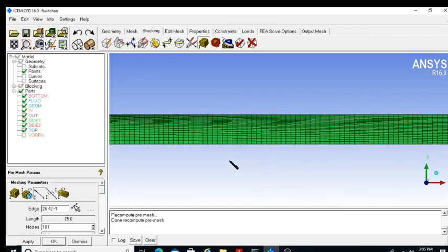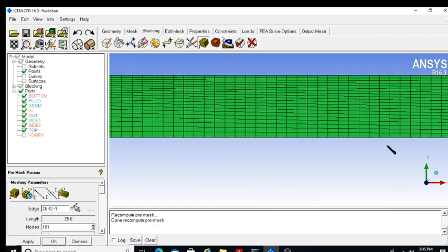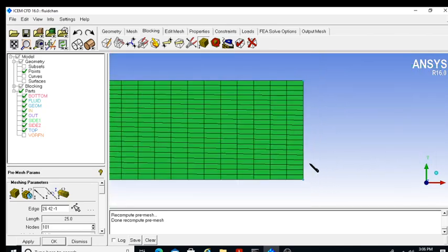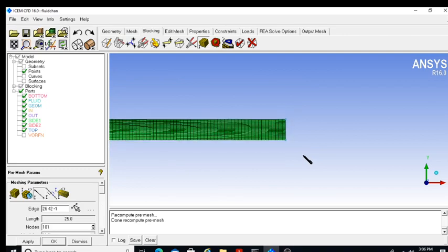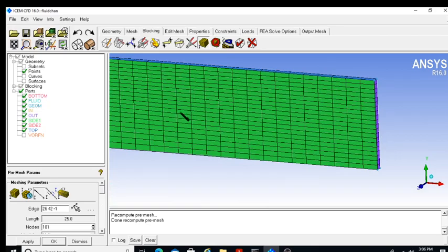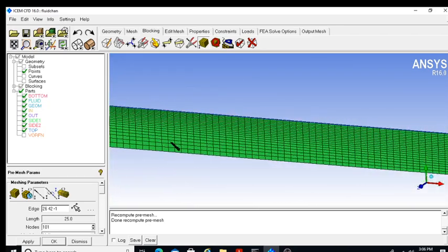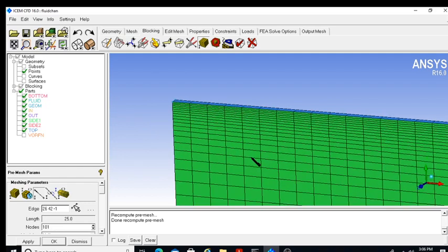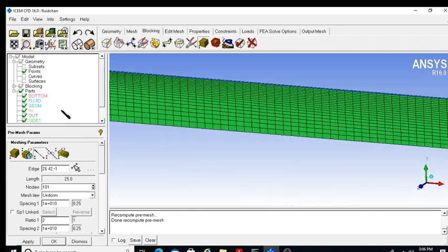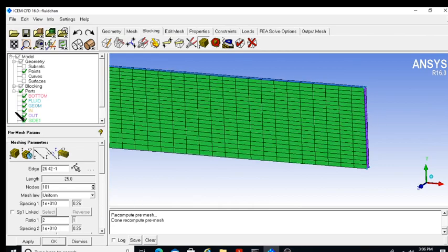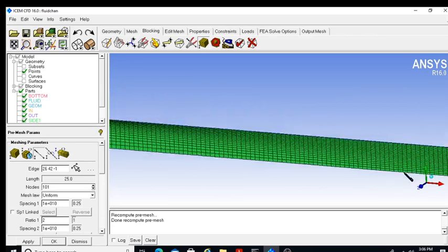I can see it from the Z-axis. So this is the mesh I have created, and it has 21 nodes in the Y direction, but they are almost all uniform actually. So it means I have changed the law here. Okay, so I need to work out, here the setting is much closer, and you see that as you are approaching, it is not the same law. It means it has not copied parameters to the parallel edges actually.